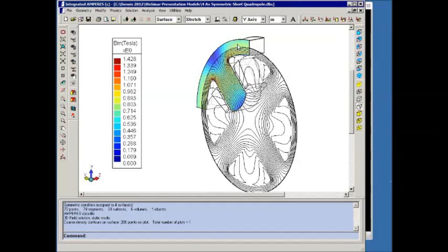When you switch plot formats, say from a contour plot of flux density to a vector potential plot, it's either one or the other, and you've lost it. And also, if you don't save your model with the plot, you've lost the plot. With the output manager, you have those plots saved until you delete them or you clear the data.